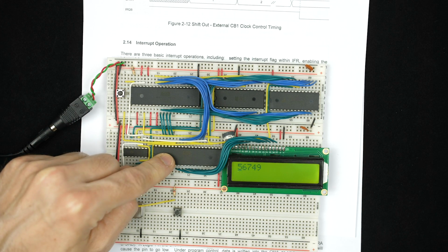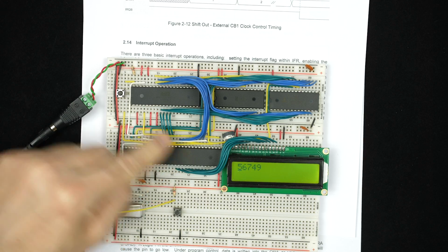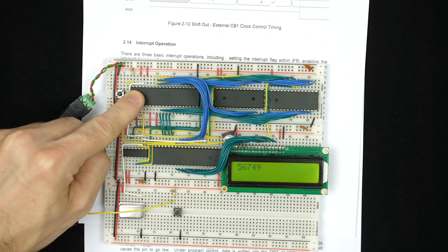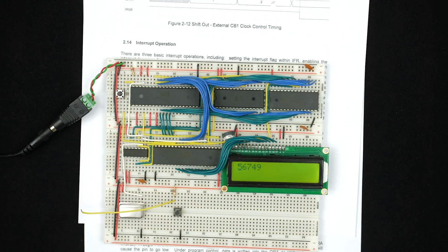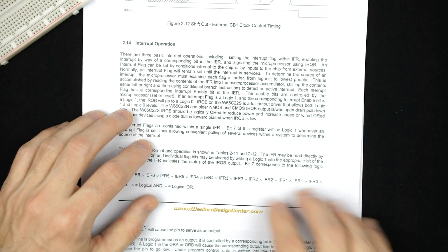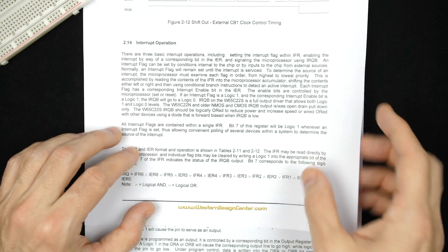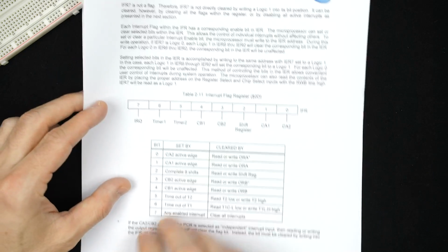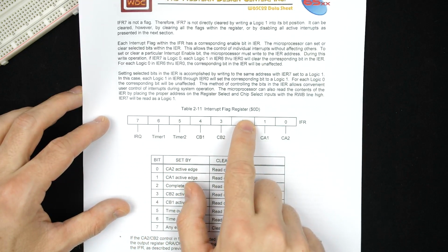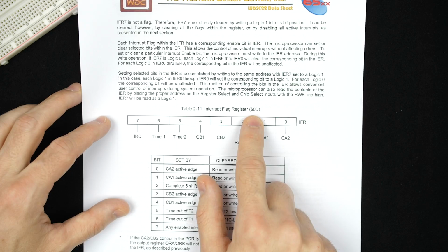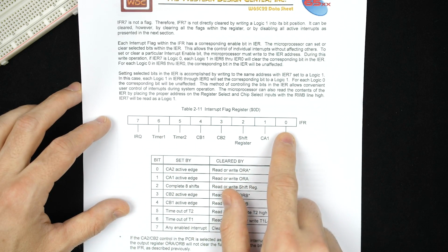So this will allow the 6522 to signal the 6502 processor when there's an interrupt, and that'll cause our interrupt handler code to run. But then we'll have to figure out what caused that interrupt. So if we look back at the interrupt operation for the 6522, it also talks about these other flags registers and so forth. And so if we look here, there's an interrupt flag register that we can read. It's at address D, which in our case would be 600D. We can read this flag register, and it will tell us what caused the interrupt.